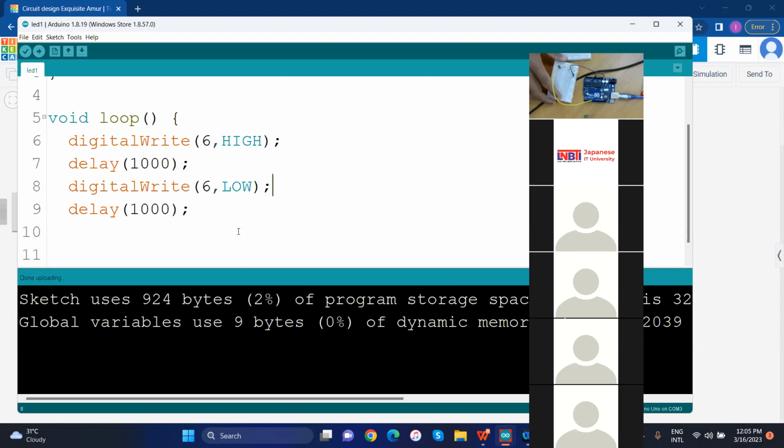Yeah, it's uploaded. When it is uploading, some LEDs will blink during the upload time. Then the LED will blink like that: 1 second switch off, 1 second switch on. If we put 300 milliseconds, then we can see the blinking is faster. We can change that delay.